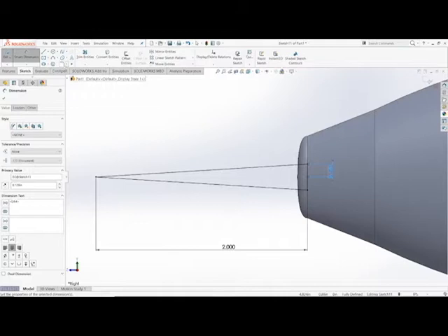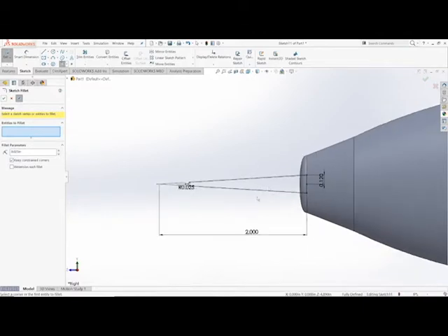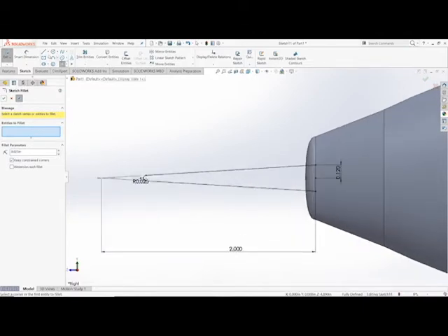That's kind of pointy. Too pointy. They are not nearly that pointy. I'm gonna make this smaller. 0.25. 0.025. That looks better. That's a sketch fillet. They look much nicer. Things look nicer when you make them right.